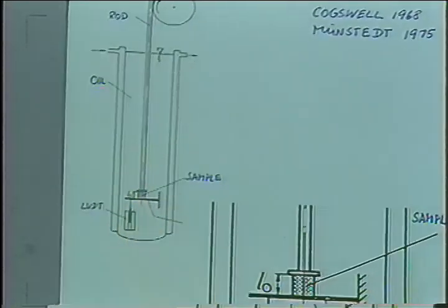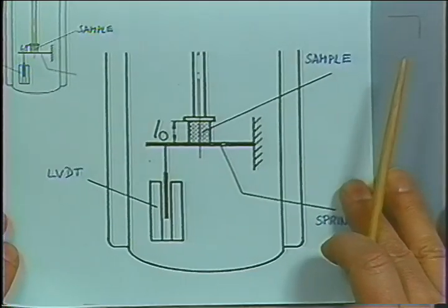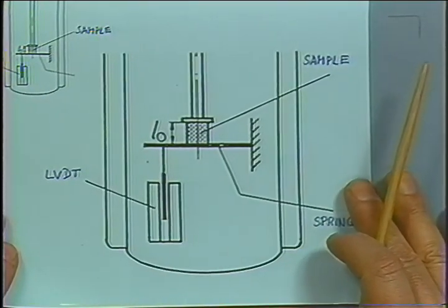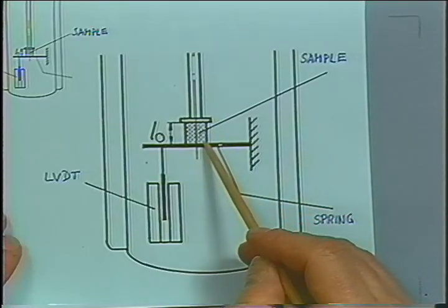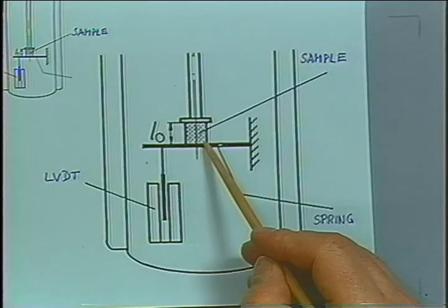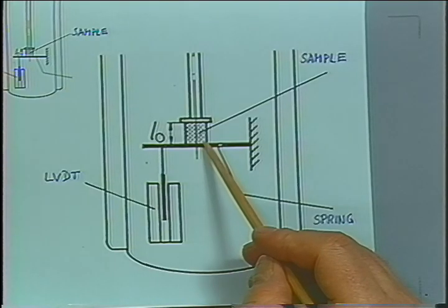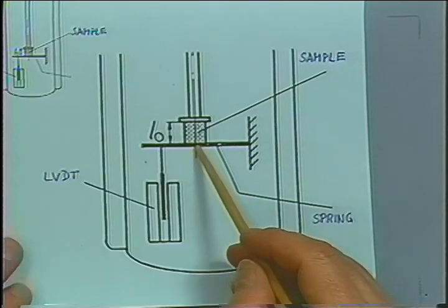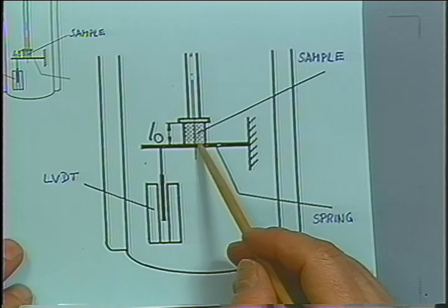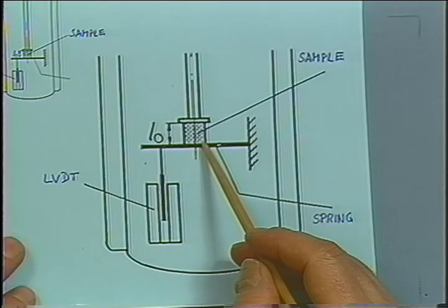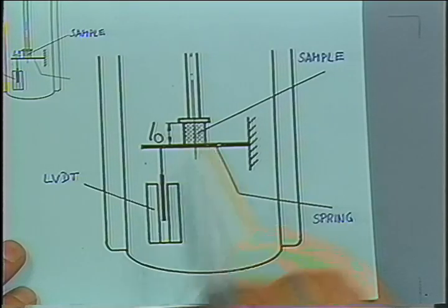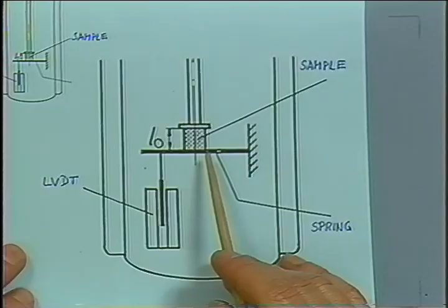Now this part I blew up here just to describe that a little further. See, this is our little sample. It's glued onto the surface. You would have to produce the cylinder first, equilibrate it so that all the structure is relaxed, all previous stresses have disappeared. And then you have to find a suitable glue which connects your polymer sample with the metal surface, and that sometimes is a hindrance, but it can be done. You use some cross-linking polymer, for instance, or super glue.